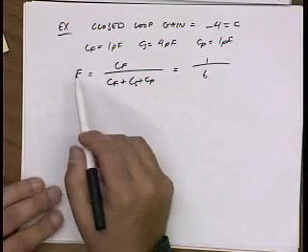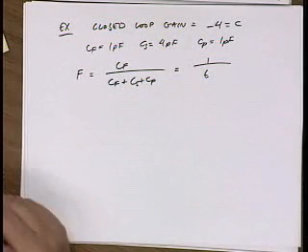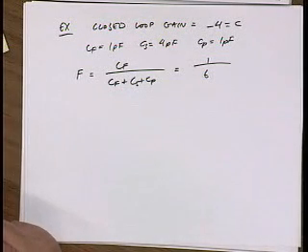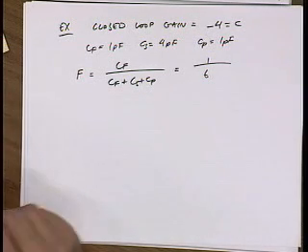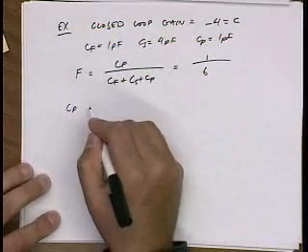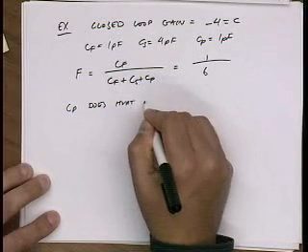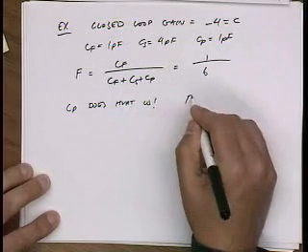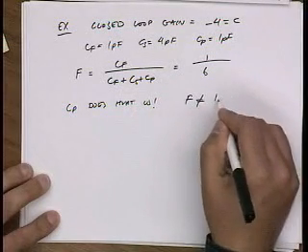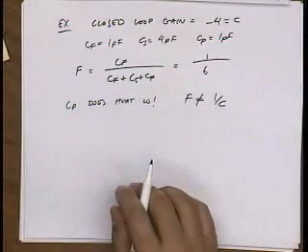Now, this is really important: F is not equal to 1 over the closed loop gain, right? 1 over the closed loop gain is 1 over 4. Here, F is 1 over 6. So this capacitance CP actually will hurt us. That's something important to take into account.